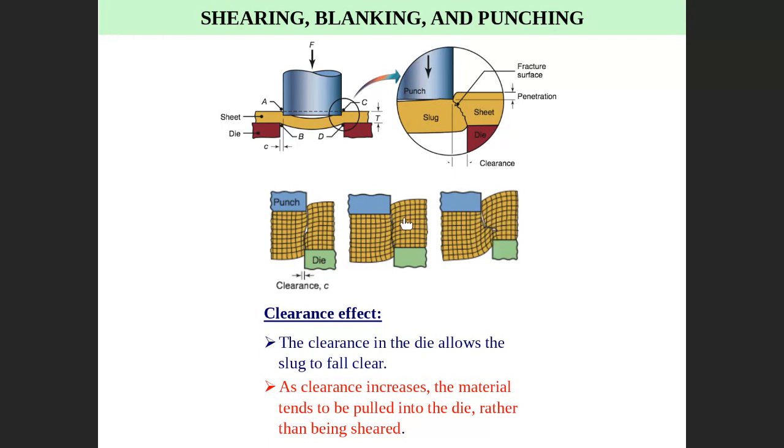Tearing happens, not shearing but tearing. You destroy the workpiece and get big distortion. So we avoid having very big clearance and very small clearance. The clearance must be adjusted in between, a correct clearance for a good and nice shearing process for cutting.